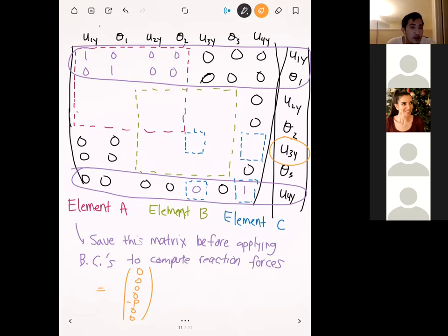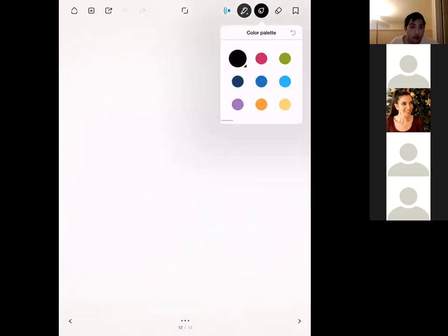Right. After you plug in all the values and solve, you get the following solution. You're going to have seven things your MATLAB is going to spit out for you. First you're going to have U1y and theta 1, and these are just going to be zeros because they're at the fixed support. You get 0 meters and 0 radians. When you solve these in MATLAB, the numbers that you get for the rotations are given to you in radians. So it'll give you a number, but the units for that is radians.